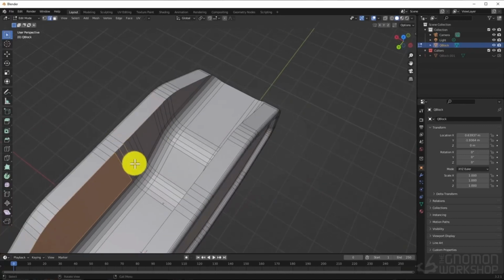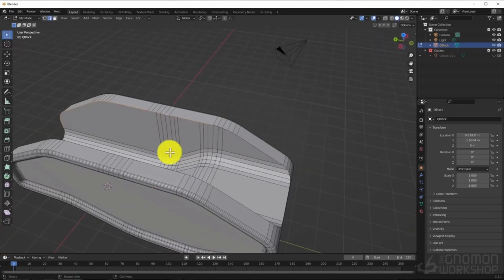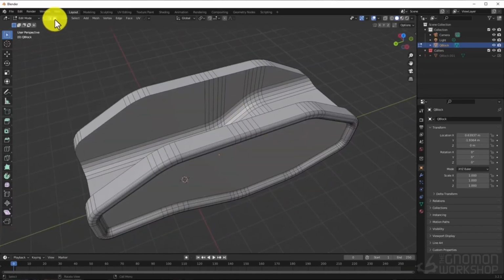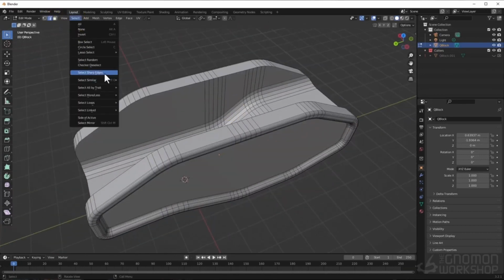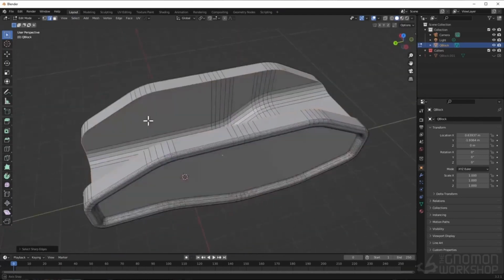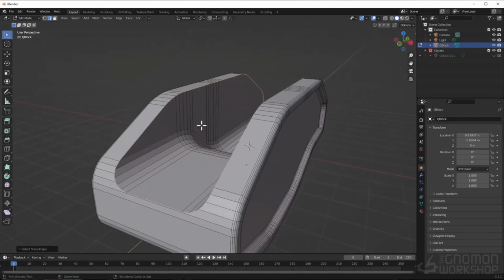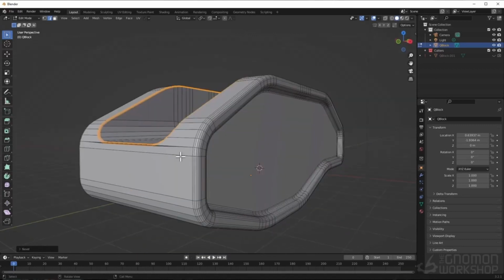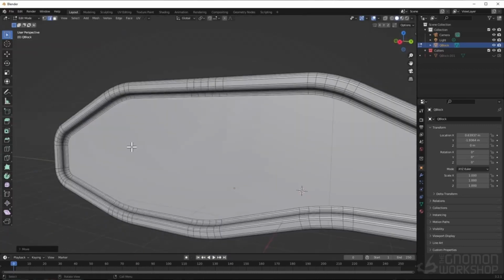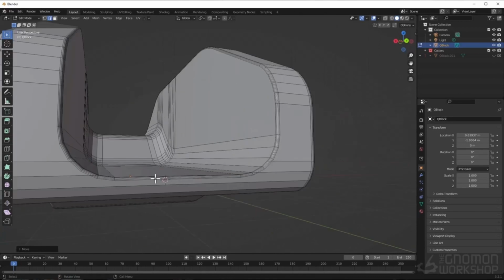Here, I'm trying to select the edges of a Boolean intersection, which doesn't usually work because of the lack of consistent edge loops, until I realise I can go to the Select menu and press Select Sharp Edges, which does the trick. Sometimes when you bevel these janky edges, you can get some overlapping and bad geometry. You can go in and fix it if it's a quick fix, but you can also fix it in Photoshop in the paint over stage. This was an easy fix, I just moved a couple of edges.